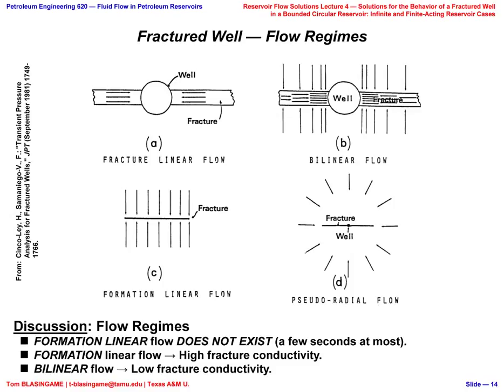Now, there are plays where choke management is absolutely critical, such as the Niobrara or the Codell Niobrara or the Eagleford, and to some degree some parts of the Delaware, where if you're not careful with your choke, you're going to bring gas on, and you're going to bring some problems. It's not a reversible process.